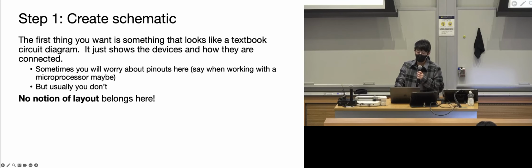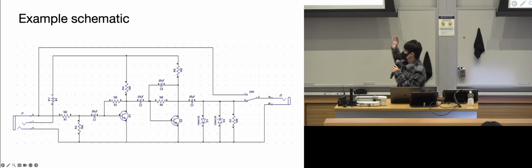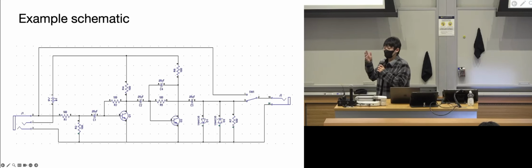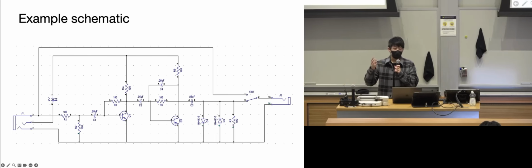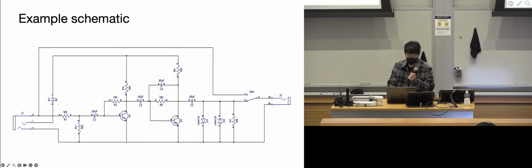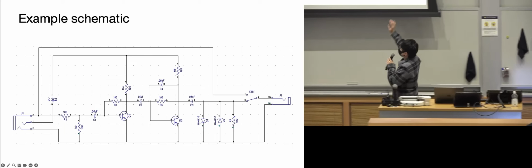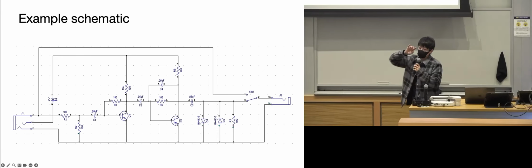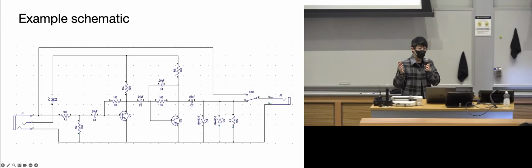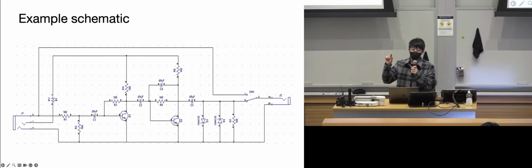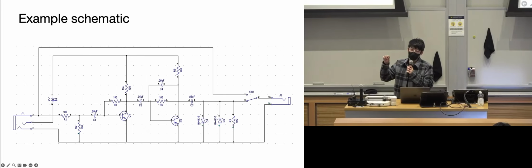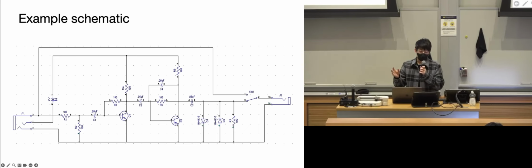So basically, you will have something that looks like this, just a schematic file that shows the list of components used in your board and how they are logically connected. Normally, you will label some of the lines as well. For example, if you use I2C or SPI, you will normally label what that signal line is, SDA, SCL, etc.